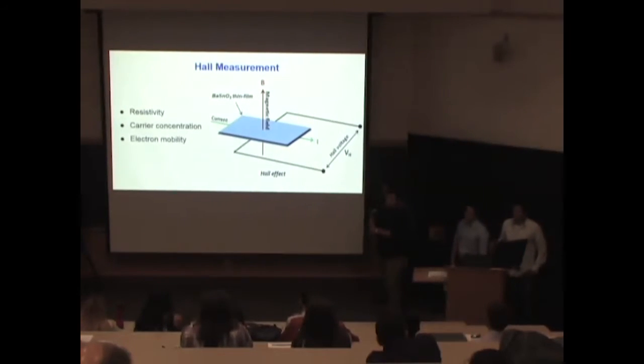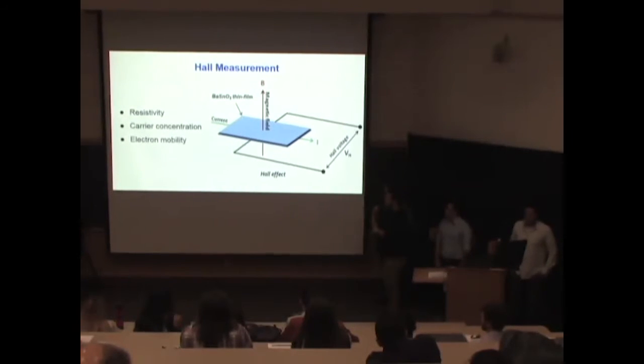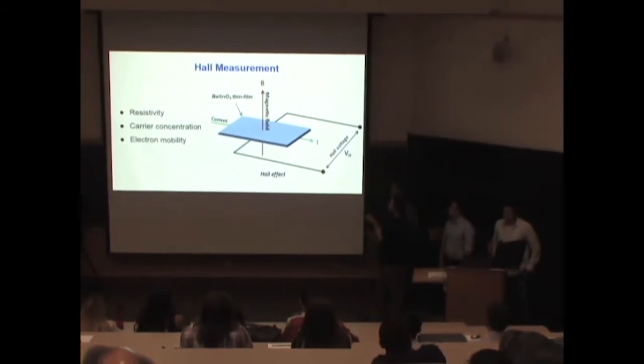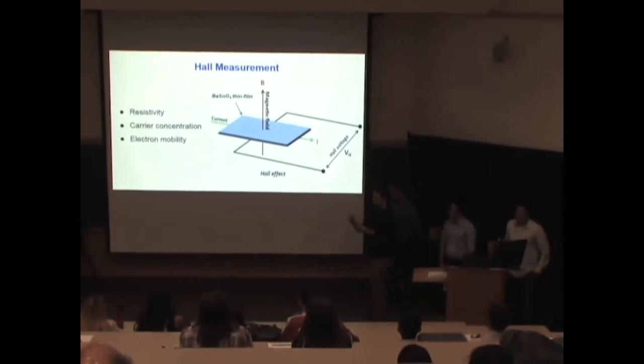And so after using AFM, we wanted to test the quality of our raw sample, and we used X-ray diffraction to test our sample. In the process of XRD, we focused X-ray beams onto our crystal film, which were then diffracted, creating diffracted X-ray beams, which are then captured by a detector, which measured the intensity and the angle of the beams.